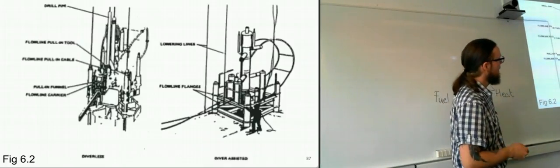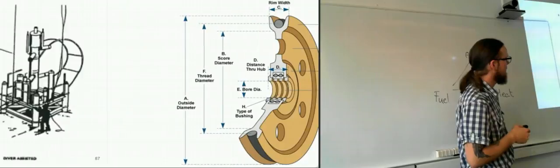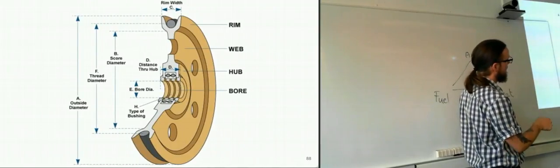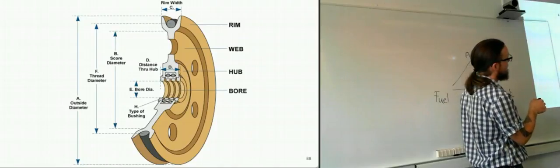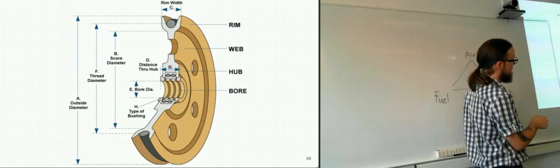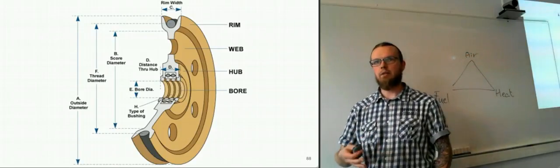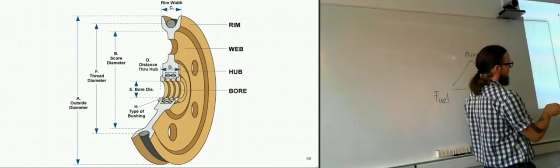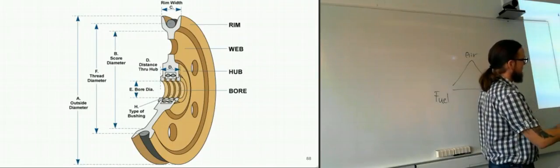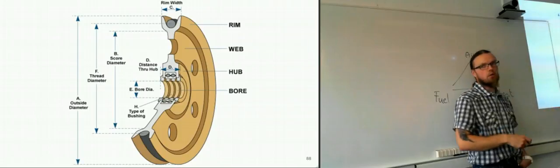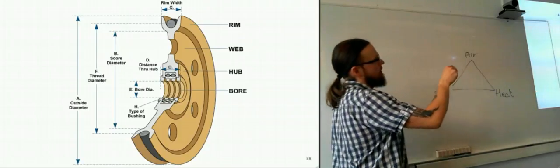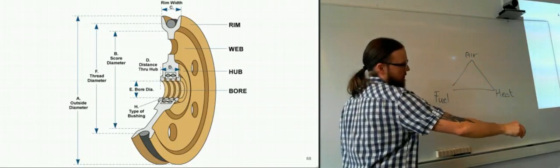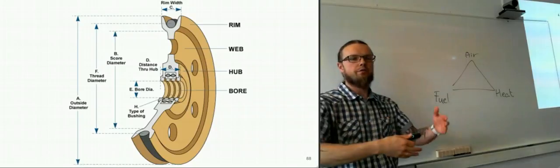And sheaves are basically just circular discs where you have a groove cut on the outer part, where you can fit in a wire or a cable or anything. And the disc rotates. It has ball bearings in here, so the disc can rotate, and then you can have this being pulled across. So if you have a winch over here pulling on this wire, it can rotate across the sheave, and then it can go down instead. So it's just a way of changing direction.